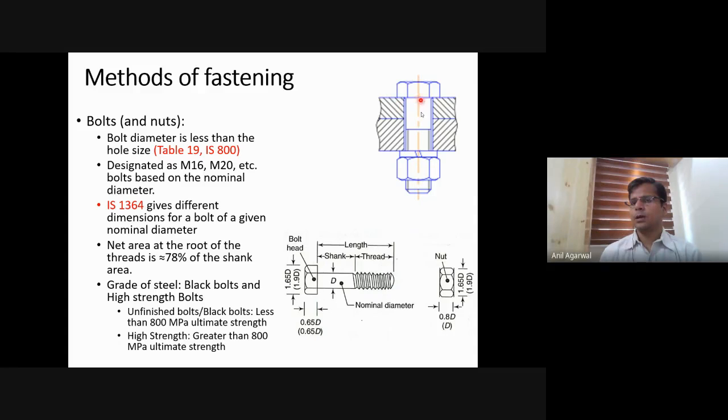That is, when you apply this tension, all that tension has to be transferred through bearing here. And if there is not enough bearing area available, this may fail. So sometimes they may realize that the bearing area is a bit dicey. They don't have enough bearing area because there is some issue with the bolt diameter. So they may provide a washer to transfer that force more effectively. But it is not necessarily used every time. It may sometimes be useful.